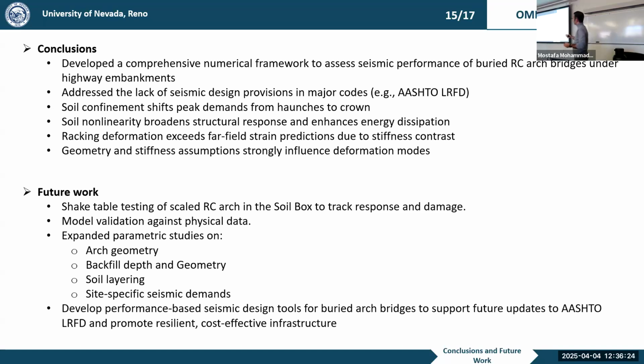We took a look at the soil confinement that shifted peak demand from the sides to the crown of our arch. And also we saw that the soil nonlinearity broadens the structural response and enhances energy dissipation. We saw those response spectra and we could conclude this. We saw that the racking deformation exceeds far-field strain prediction due to stiffness contrast.